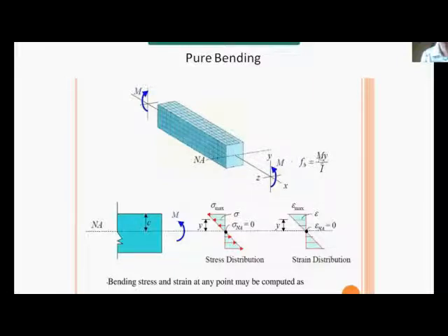So you get bending moment in two different planes. So it is called unsymmetric bending. If it is not along the axis of symmetry, we call it unsymmetric bending. In other words, we call these two axes the principal axes of inertia. About this axis, that is along the axis parallel to width, you get maximum moment.